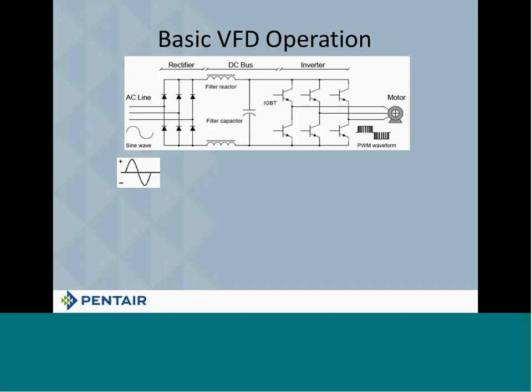Now, how does the drive work? I was talking to Ted earlier today, and the way this goes is it doesn't matter what the drive is. Okay? It doesn't matter whose drive it is. If it is a variable frequency drive, the way that it works is this. It takes AC power in. Now that's an AC sine wave right there. You can put 3-phase power in. You can put single-phase power in.